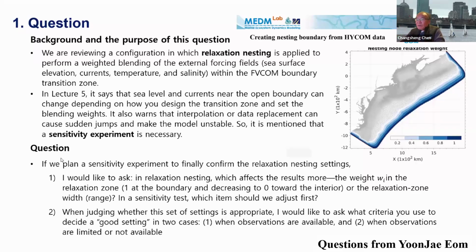But with the transition, we found the HYCOM model doesn't include tide when we run that. That's the reason we had to add a tide model and put in the low frequency, because without tide, the circulation comes out very different from the case with tide. That's why we had to do a transition and put the low frequency in. That really depends on the location you want to study.